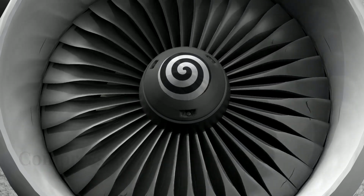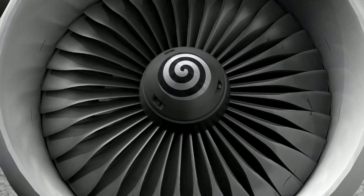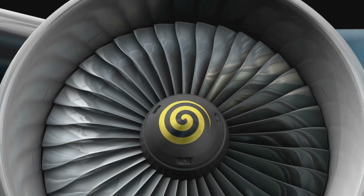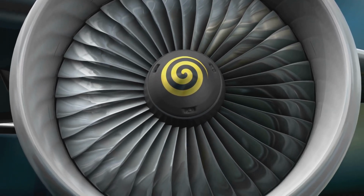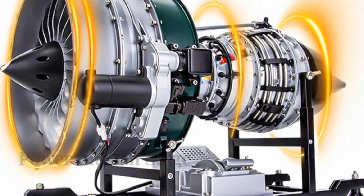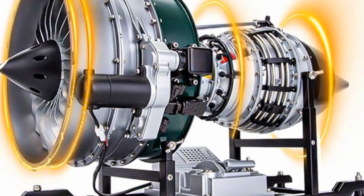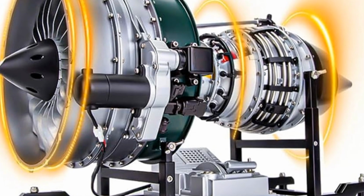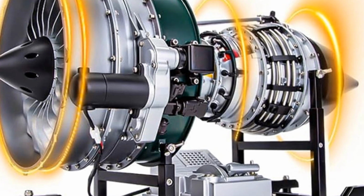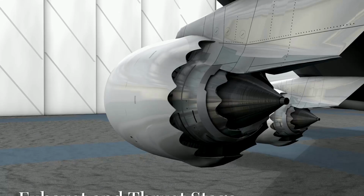2. Compress and combust. The air entering the core is compressed by a series of compressors, then mixed with fuel and ignited in the combustion chamber. 3. Power the fan. The hot, expanding gases from combustion flow through turbines, which spin and power both the compressors and the large fan at the front via a shaft.